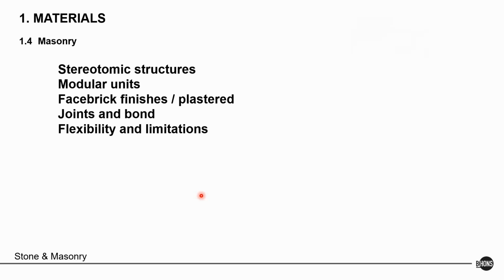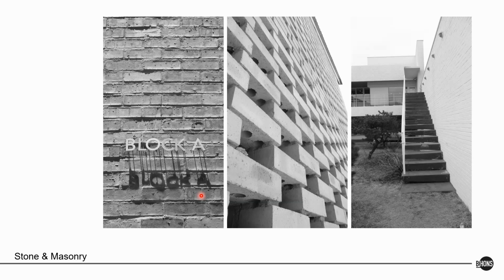The one thing to think about in terms of masonry is that there are certainly limitations to how high you can build a masonry wall and how long you can build it without having brace walls or buttress walls and so forth. So go and have a look at that. It's specified in the SANS standards, but don't forget that. We spoke about the plastering of it, whether you can use bag washed plasters or smooth plasters or scratch plasters. All of them have different ways of articulating it. It's simply beautiful the way you can use it, but you must define it and specify it when you design it, and don't ignore it in the end.